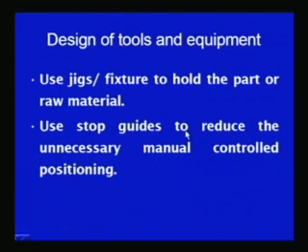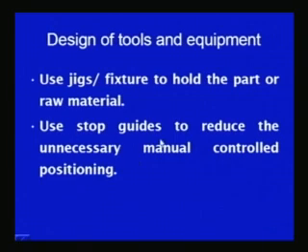Use stop guides to reduce unnecessary manually controlled positioning. Stops should be used as and when possible, so that manually it will not be required to start, stop or control the motions as per requirement. The systems will automatically respond if stops and guides are used, and that will help to avoid unnecessary manually controlled positioning of the tool or the workpiece during the operation.